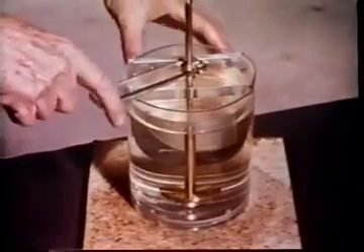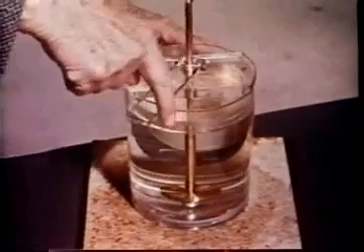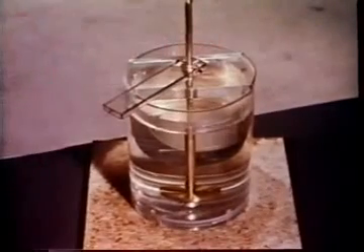Low-Reynolds number flows are reversible when the direction of motion of the boundaries which gave rise to the flow is reversed. This may lead to some surprising situations which might almost make one believe that the fluid has a memory of its own. Here are 2 concentric cylinders. The fluid can be moved by turning the inner cylinder with this handle. The annulus between them is filled with glycerine.